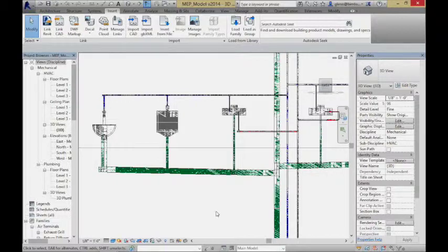Now, the size of the sanitary line coming out of each of those fixtures is a little bit different. For the toilets, they're typically 3 or 4 inches. It's much bigger because you have to remove solid waste, so you need big systems to carry away the waste. A urinal, since we don't have solid waste, tends to have a much smaller line, maybe a 1.5 inch line or something like that. Same thing with a sink. A sink tends to have a fairly small drain line coming away from it.